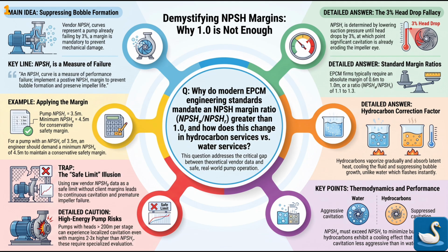The implication of that gradual stew vaporization is a thermodynamic cooling effect. As the lighter components in a hydrocarbon mixture begin to vaporize and form bubbles, they absorb latent heat from the surrounding unvaporized fluid. Right. This local heat absorption actually cools the immediate fluid slightly, which in turn drops the localized vapor pressure and suppresses any further bubble growth. Interesting. Because the cavitation is inherently less aggressive and self-limiting compared to pure water services, it allows for a mathematically lower structural risk.